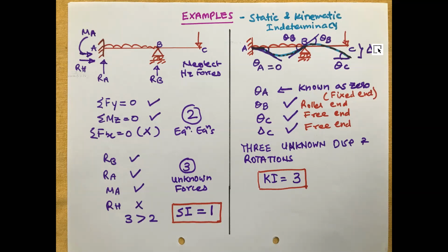Whatever unknown quantity, I can put it in one category. And also there will be a rotation. You can check this experiment by rotating the paper. You can check this where there is a rotation along with deflection. So the free support will have rotation as well as deflection. So here there are two quantities and support B can rotate, so 3.